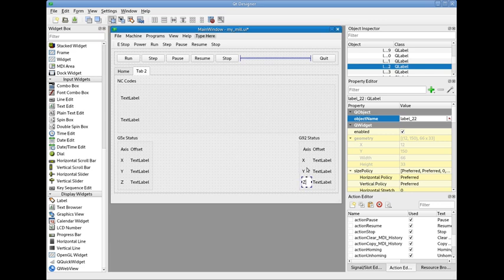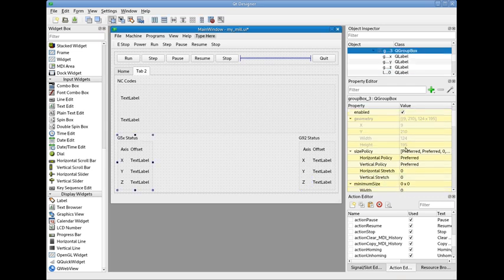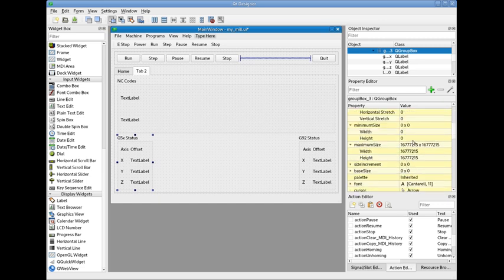It's only as wide as it needs to be when you have that layout alignment set. So now let's set the minimum width. Oops, not 2003, 200. Hit enter key, and you can see that got wider.